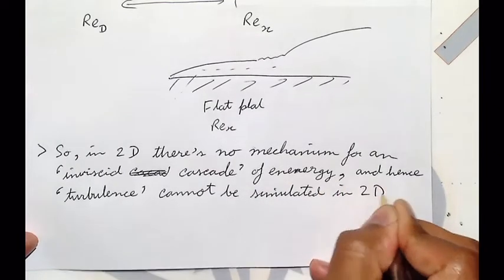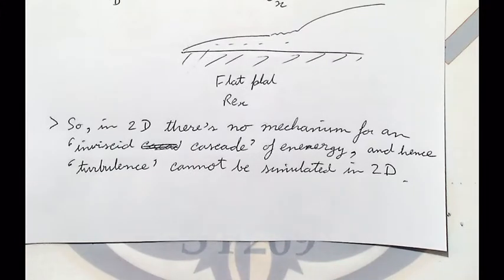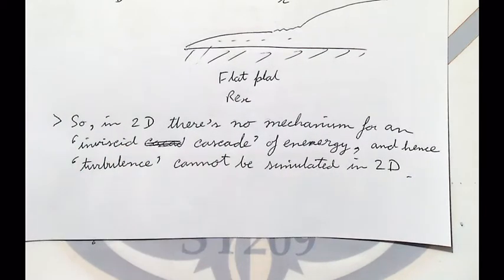And again, remember, turbulence does not mean unsteady flow or disturbed flow. It's very specific to whether or not this inviscid cascade exists. But for example, turbulence intensity can be defined, right? Yeah, you can define that's your u prime squared over 2. Of course, you can say my mean velocity subtracted from everything gives me u prime. It's just a fluctuation kind of energy. Okay.